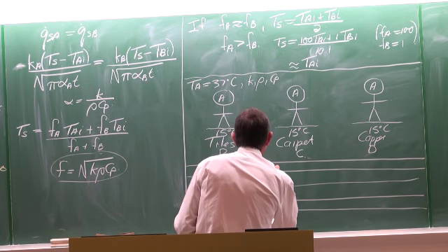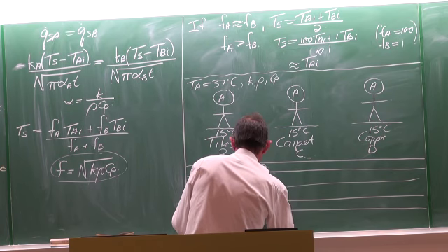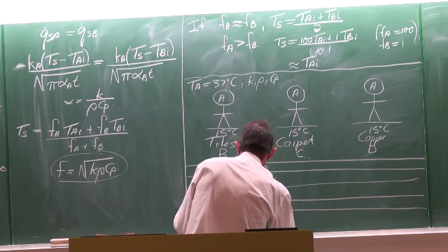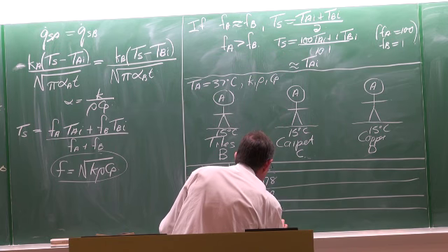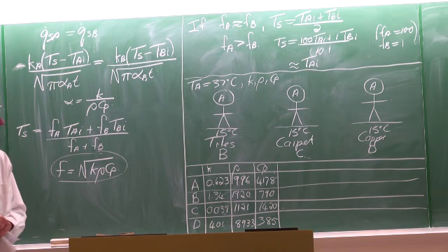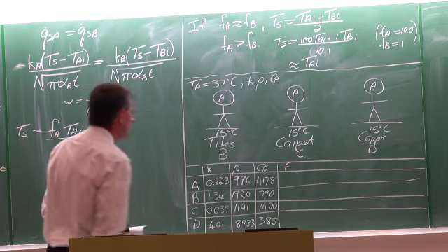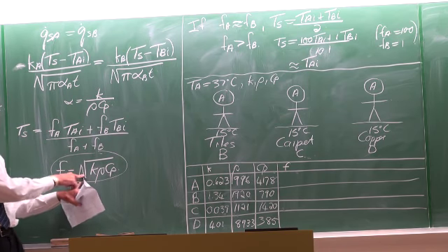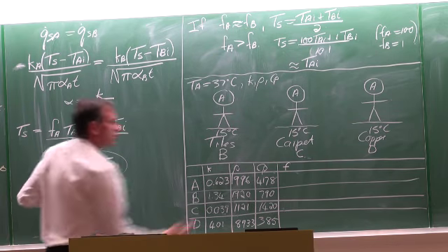The Cp values would be equal to 4178, 790, 1420, and 385. Now if we go and calculate the F values, what is F again? F is just the square root of K multiplied by rho multiplied by Cp.